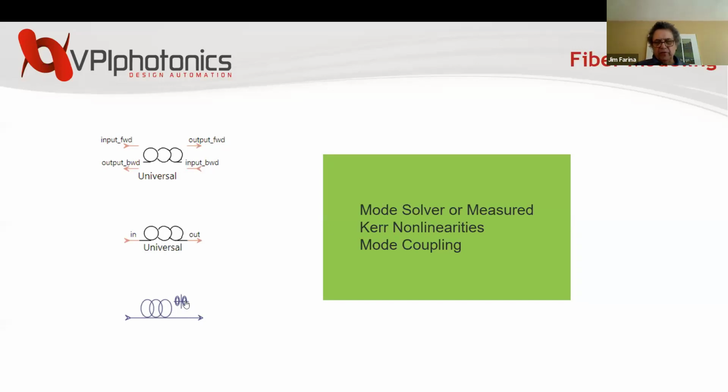Then also multi-mode fibers. For the multi-mode fiber, you use a mode solver or measured data to get the characteristics of the fiber itself, and it uses that to characterize the fiber and calculate all the propagation. It takes into account Kerr nonlinearities as well as mode coupling.